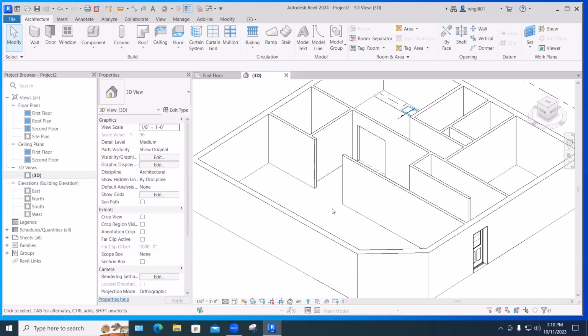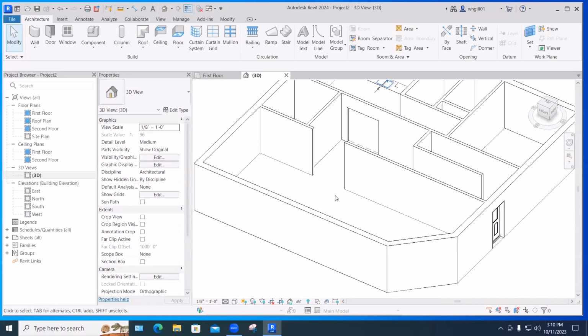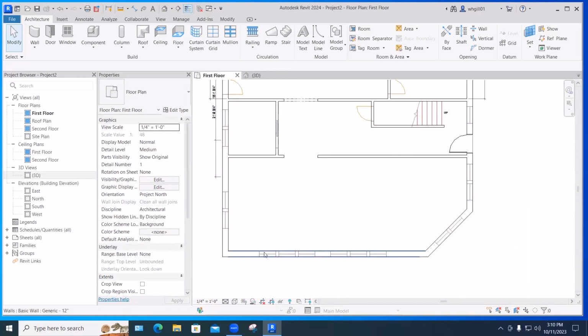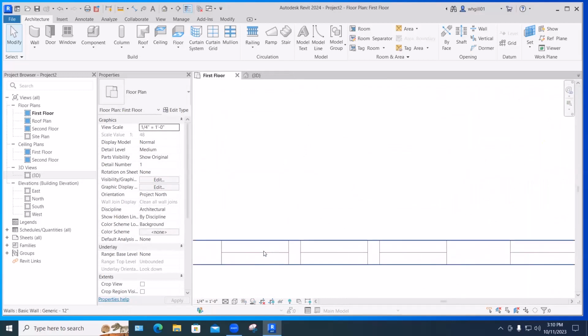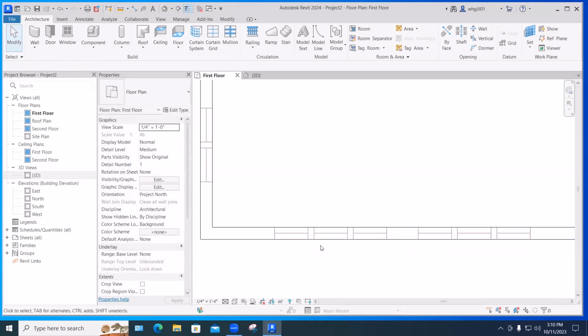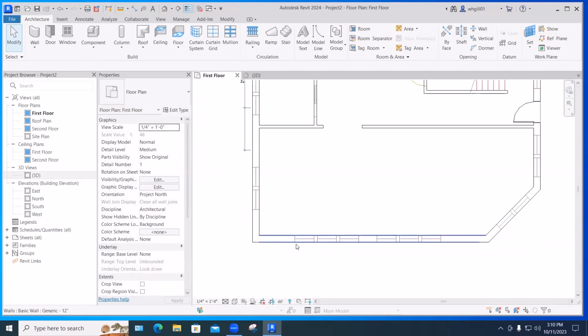Okay, we'll start wrapping this up. Doors, we know. Let's deal with windows because they have the additional thing of not only styles, but actually heights off the floor. Let's do these down here. Let's see how wide they are first. 2'10". And I said on here, these are casement windows, which swing open. So we'll have to decide on a swing, but let's get them in there first.